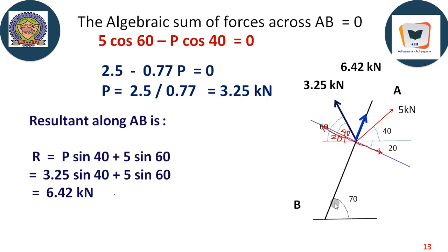That means to say the effect of the resultant along this particular line is 0. Therefore, the sum of the horizontal components of these two forces equal to 0. That is the logic of this particular problem. To conclude, this tutorial clearly explained how we can find the resultant in a concurrent force system, of course a coplanar concurrent force system. It is very important to realize such systems will be in a state of imbalance. Any system, as a matter of fact, if it possesses a resultant, it will be in a state of imbalance, because there can be a horizontal jerk, there can be a vertical jerk.